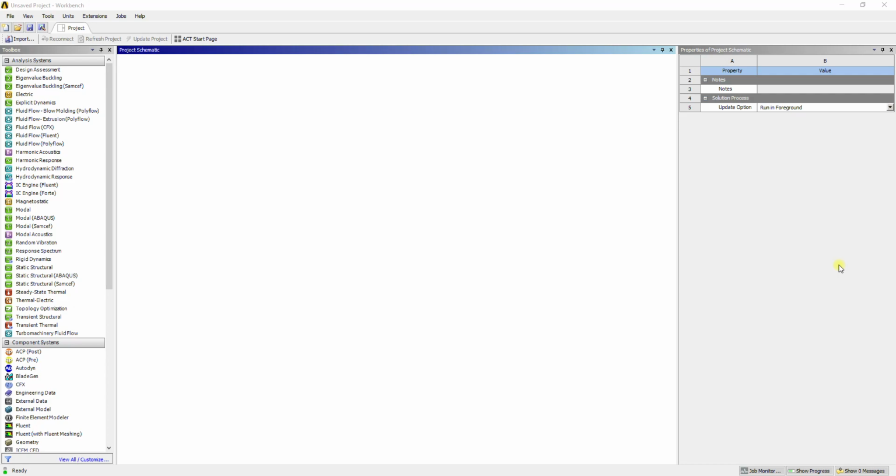Today we are going to make a validation of nonlinear buckling analysis of sub-stiffened plates. When we are doing that, we will use the Johnson-Cook plasticity formulation. Also, we are not going to apply the eigenvalue buckling analysis step. We will use a faster and easier method to find the ultimate buckling load, because today we are going to find the ultimate buckling load, but with this method we cannot find the critical buckling load.